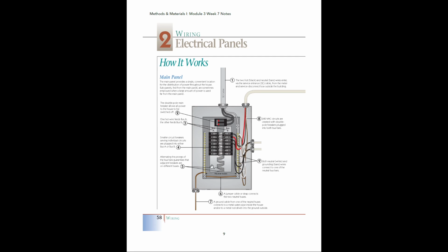These individual breakers are tied to the individual circuits that are running through the house. So if you were to flip one of these off, it might turn off only the lights upstairs or only the lights in the kitchen, something like that. And these will trip, meaning they will automatically shut themselves off if they detect an overload in the circuit. If too much electricity is being pulled at once along the circuit, these are going to sense that and say, nope, that's dangerous, and automatically flip themselves off and prevent an accident from occurring, okay?